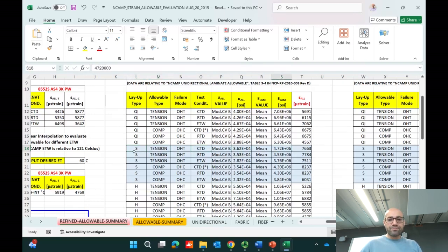The same can be done in cold temperature dry, where D means dry: cold temperature dry, room temperature dry, elevated temperature wet. High temperatures and wetness are bad for aircraft, for any structure, so this is the worst case scenario. Room temperature is like this, at room temperature and ambient moisture we just measure the composite as well. Also, cold temperature makes the composite brittle. If you look at the strain values, all of these would be calculated on different laminates. We've done it on hard laminates as well, very tough laminates, all 0 and 90. You can see it.